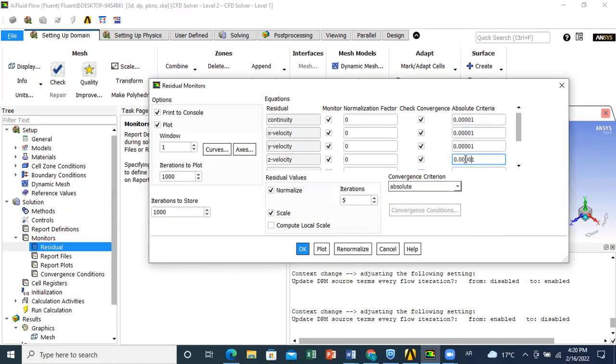And anyway, you can stop your simulation at any time and see your results. So even if you didn't reach the values that you set initially, 10^-5, you can say, for example, when you reach 10^-4 and you obtain a physical solution that seems logical, you can stop then. And as I told you, the validation process will always help you to know to what extent you can consider that your solution has converged.